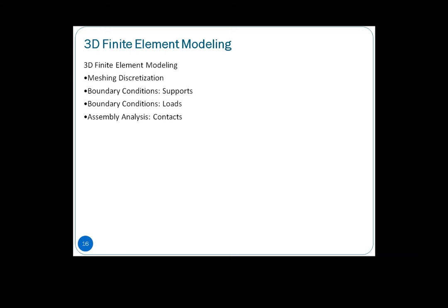its physical behavior. Then we are dealing with the supports, the boundary conditions, the loads, and if you are having a multi-component, then the contact is also important. So contact between the two components coming into play is also important. So those are the things that we have to look into.